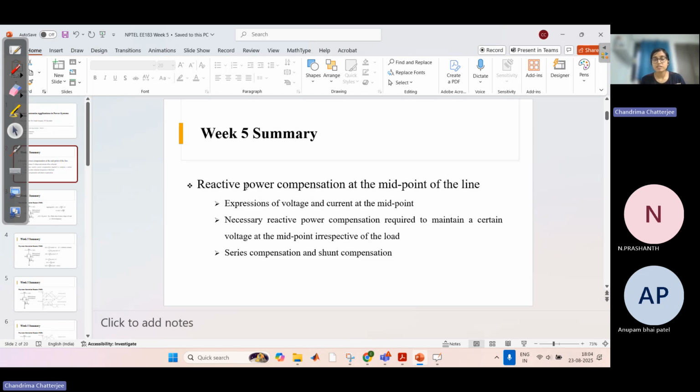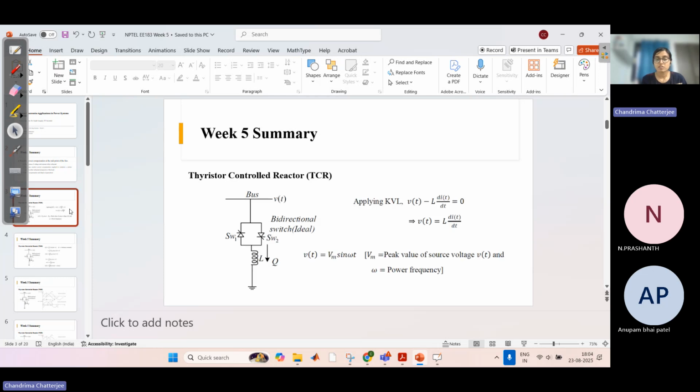When it is required to absorb the reactive power during light load condition, we need inductive reactance, which is basically an inductor, and when there is an under voltage and we require to provide reactive power, then we need capacitive reactance, right? So we need a capacitor bank or something like this. Today we shall see in detail what we usually do to achieve that reactive power compensation.